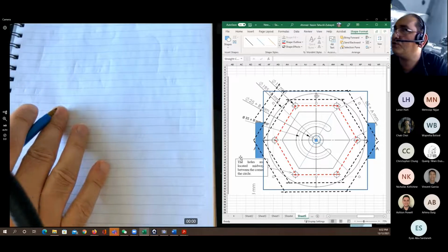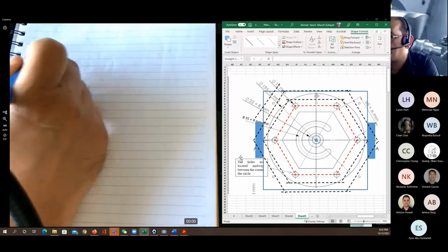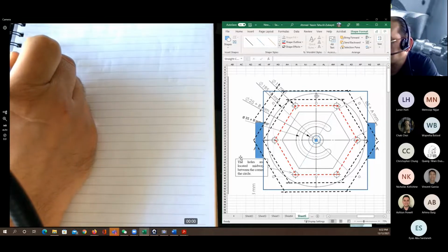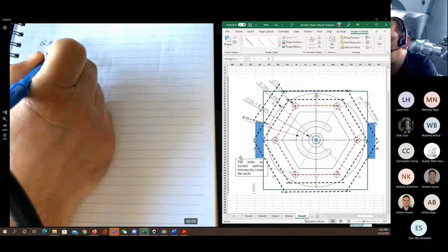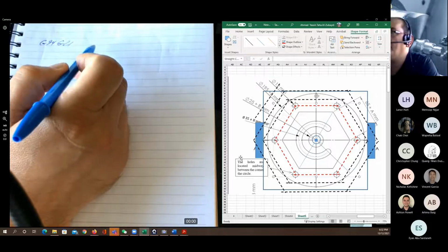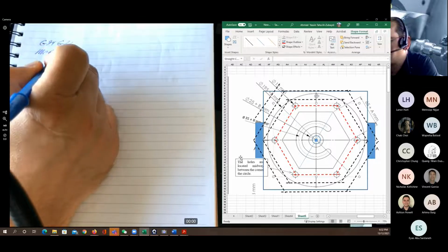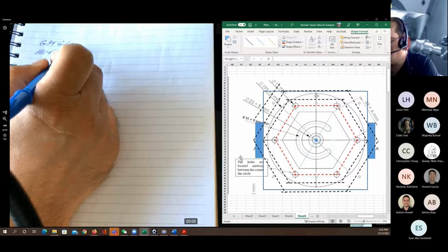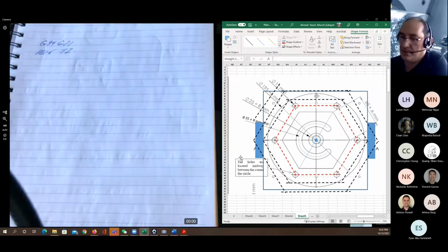So the first thing I'm going to do is, of course, I need to define G94 and G21 and M06. Use the tool number 2. I choose the tool number 2 because this will be a larger one.